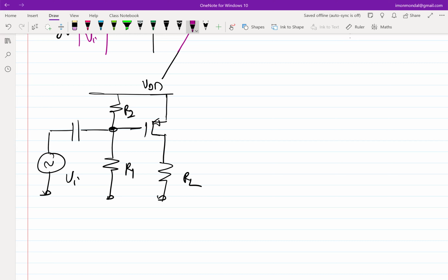There is a transference of power from the electronic to the acoustic domain. So when you equate these two powers and translate that power in the electronic domain, you will get some V squared times some effective R, because power means V squared over some effective R. If you have a voltage, there has to be an R, otherwise there is no power. So it's not an absolute resistance, it's a model resistance. What I essentially mean is that you don't have this effective RL. That RL is a model. So that is an example.